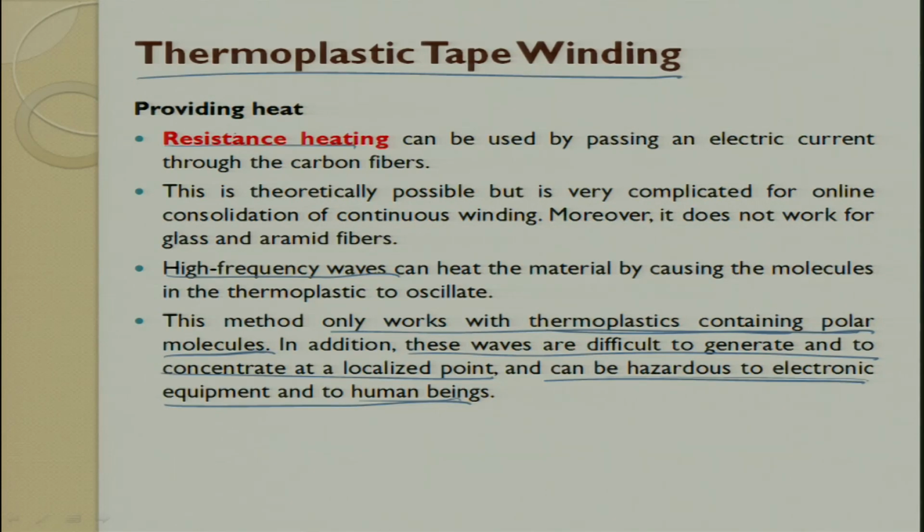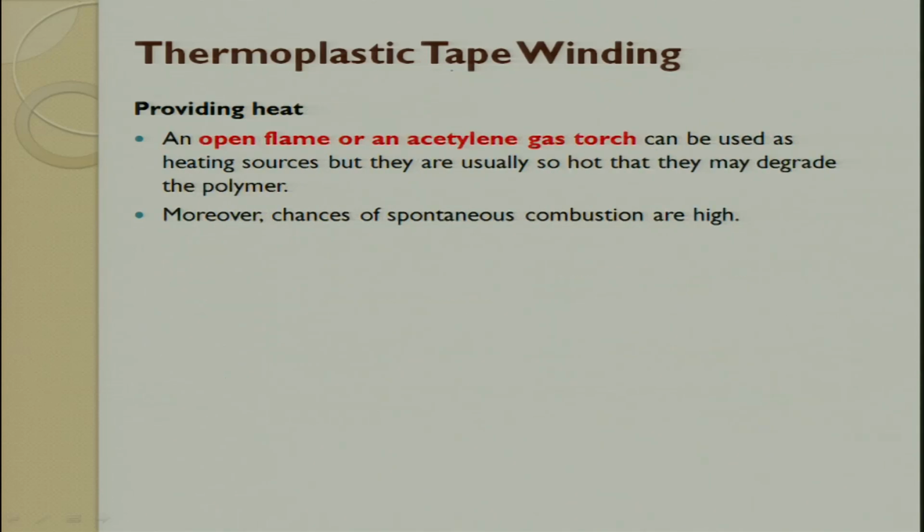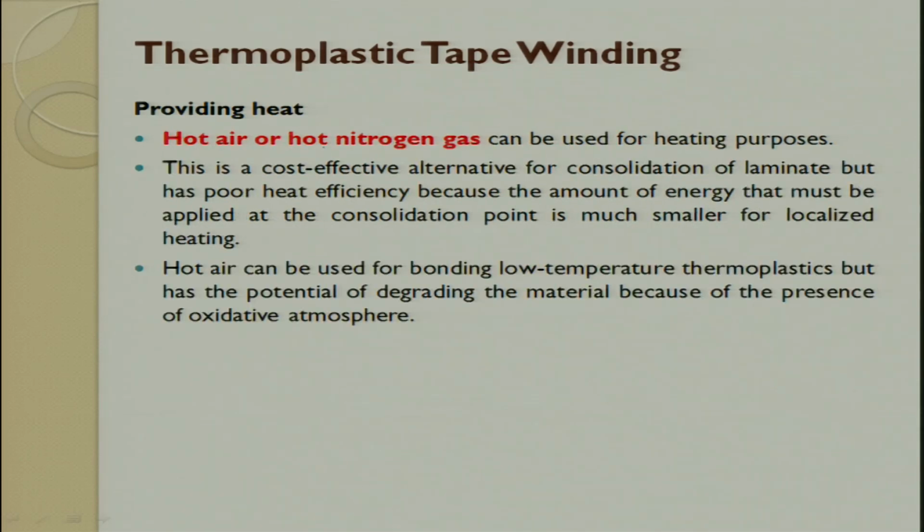The only thing I want to say is that heating can be done by laser, by resistance, or by high frequency. We always go for laser. If you want, you can also try other ways of doing it. You can also use an open flame, but it is not focused at a point, so you cannot have better consolidation.